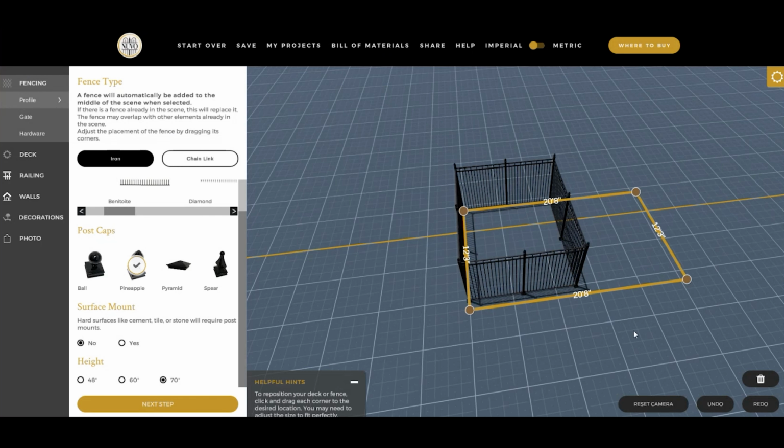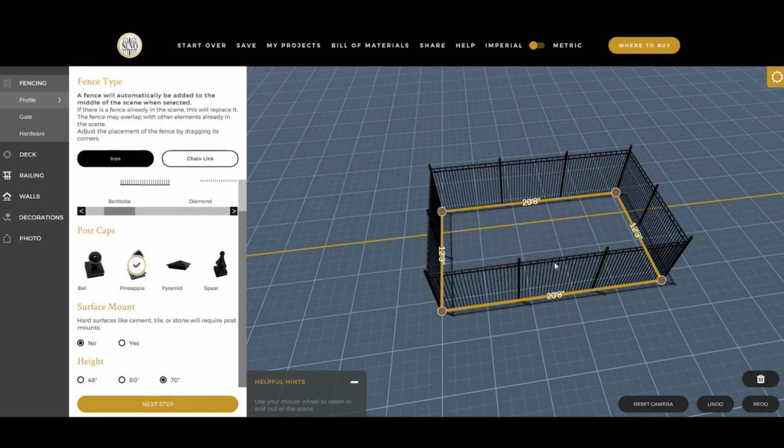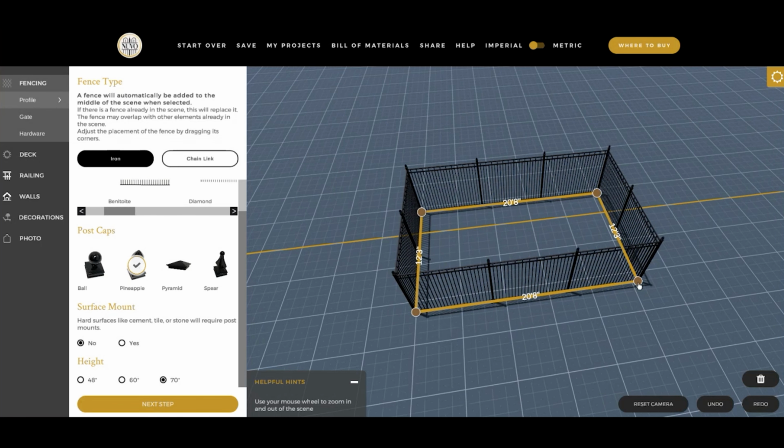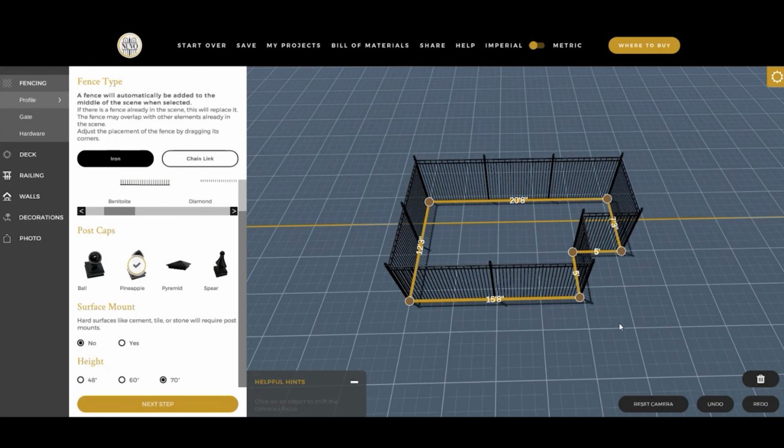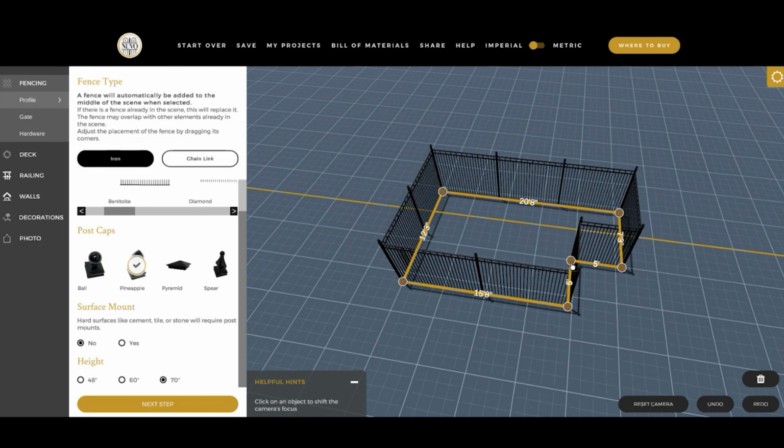Okay, so if I need to make some additional changes to the shape, the control points themselves you can click and release, and you have another set of options available to you. So if I want to select notch, you can see what that does here. It's going to notch that corner and gives us some additional points so we can further adjust that shape as needed.